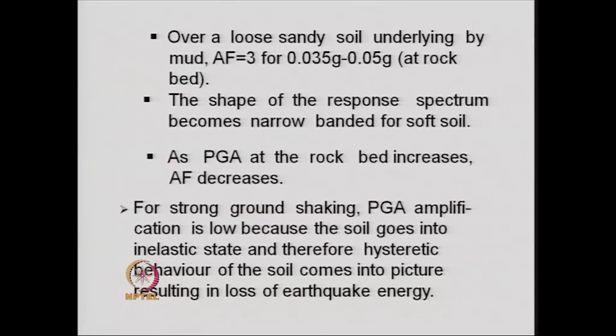The shape of the response spectrum became narrow banded for soft soil, and finally it was observed that if the peak ground acceleration at the rock bed increases, then the amplification factor decreases.